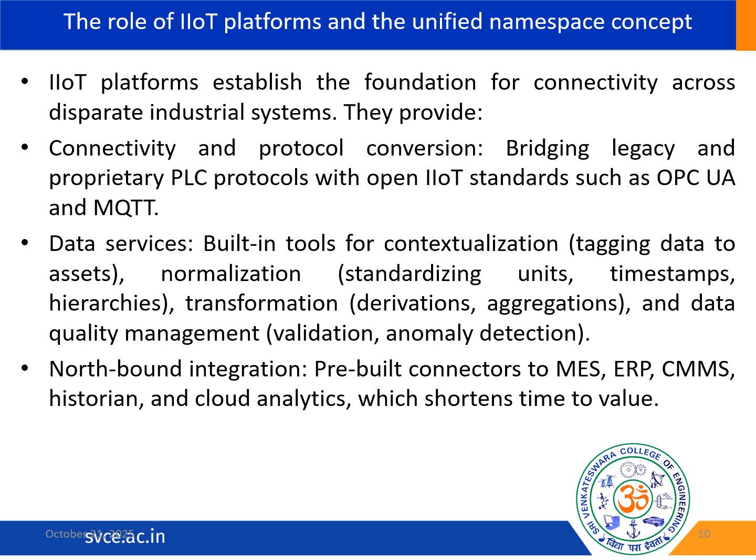So here we will be considering the role of IIoT platforms with three standards. First is connectivity and protocol conversion, which bridges legacy and PLC protocols with open IIoT standards such as OPC UA and MQTT.